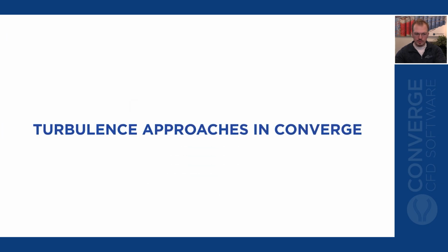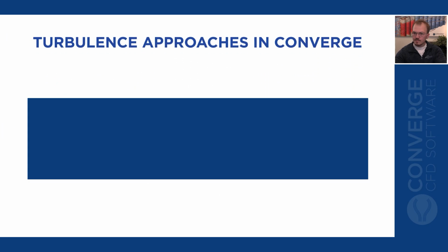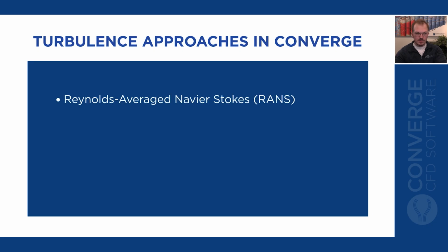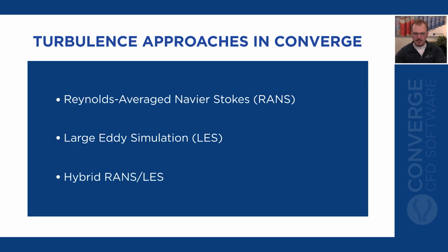CONVERGE offers three approaches for modeling turbulence: the Reynolds Averaged Navier-Stokes, or RANS, the Large Eddy Simulation, or LES, and a RANS-LES hybrid. CONVERGE includes several models for each of these approaches, which we'll now discuss in more detail.